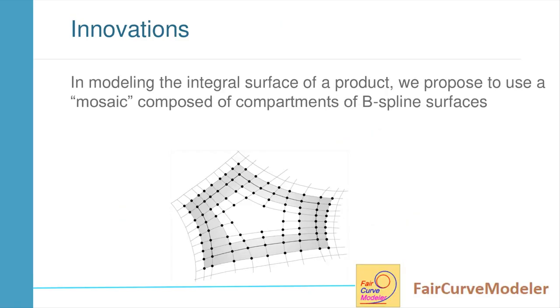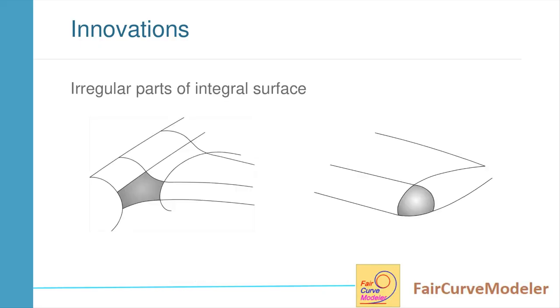In this technique, adjacent compartments share subareas of floating S-frames to ensure overall smoothness. In addition, a technique for matching B surfaces by constructing them on a base point network was developed. When modeling topologically complex surfaces as mosaic of B-surf, areas that are not homeomorphic to the rectangle inevitably arise. Such areas arise at the fuselage wing junction and on the wing tip. Such areas arise at the junction of the vessel's bulb with bow.